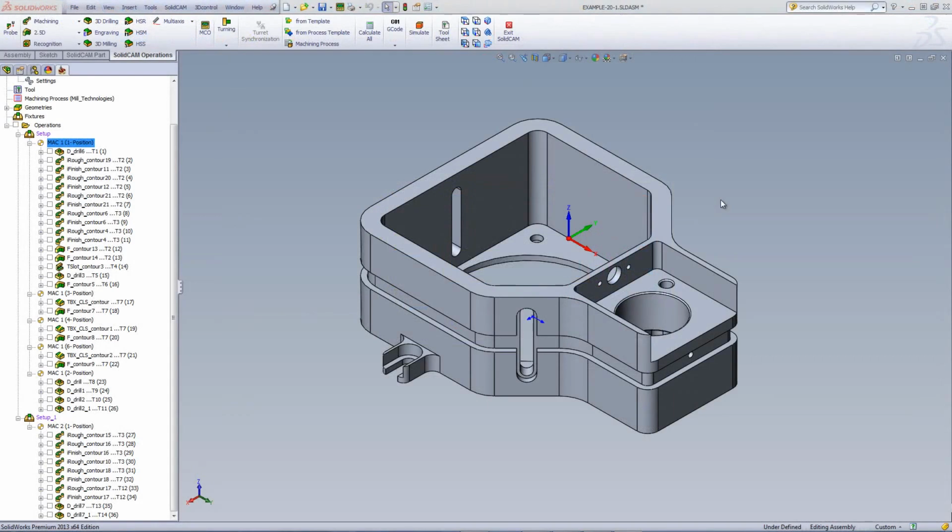In this recording, we'll demonstrate the use of 2.5D machining operations in order to mill this entire part. If we take a look at the part itself, you'll note that it has many different types of features on it. First, we have deep pockets that have to be milled out. We have holes that have to be milled out or drilled out. We have this slot around the part itself that we can use our T-slot operation to mill out.